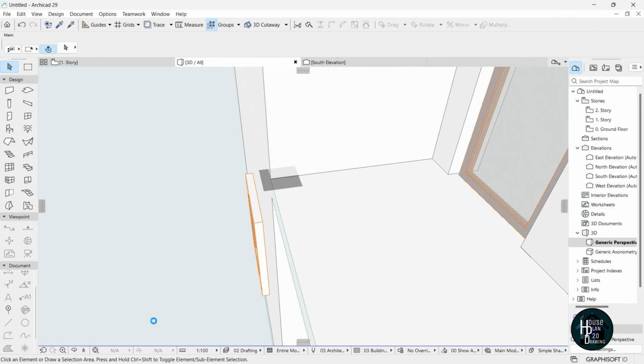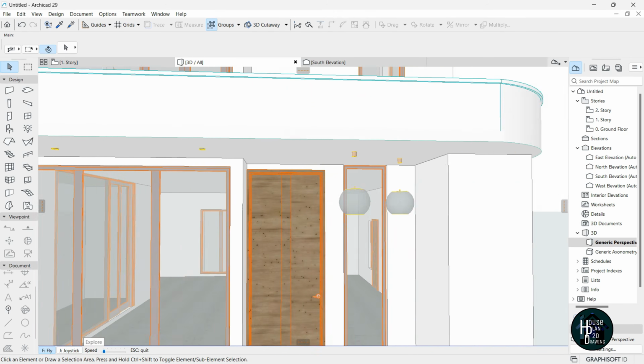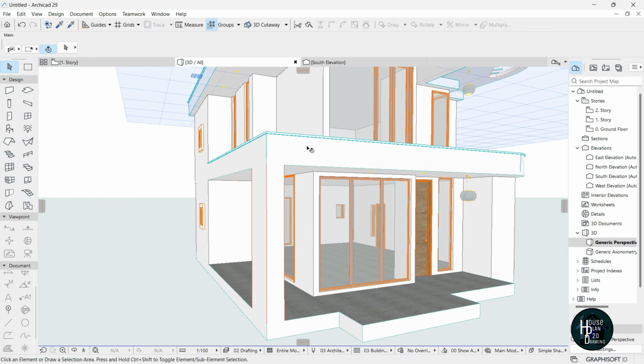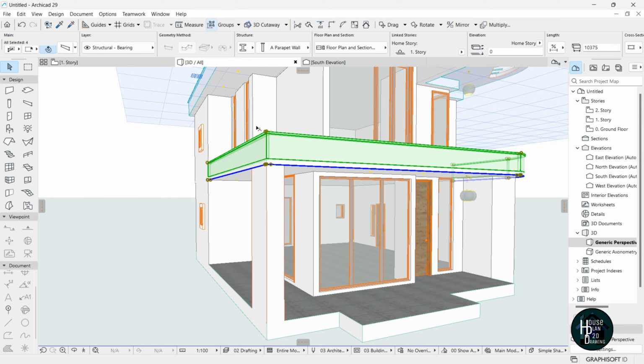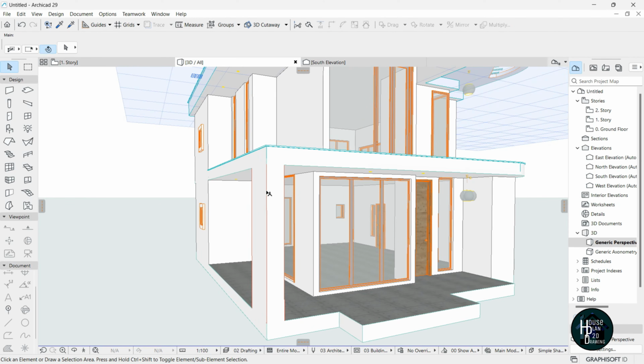You should have that design for the parapet wall being shown, as you can see, and this side is also curved. You can decide to reduce the height of this. Click this, untick your suspend groups, click on the settings dialog again, and instead of this height, let's give it a height of 500. Click enter. So as you can see, that shortens like this.